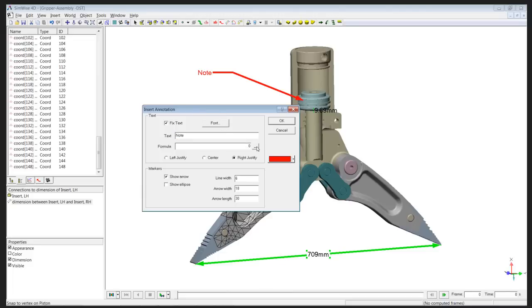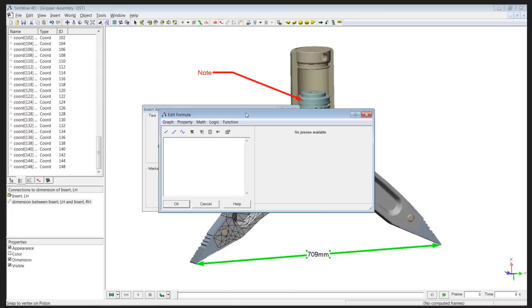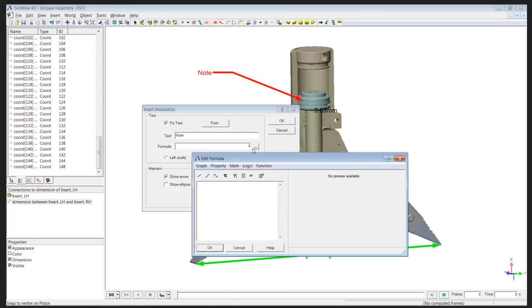So what we'll do is we're going to add an annotation, and this is going to be a real-time math-based annotation that reads the mechanical advantage, or the input versus output ratio, of the clamp. So we have our function builder here, and I'm going to take the constraint force, constraint 154. That was the constraint number for our actuator.